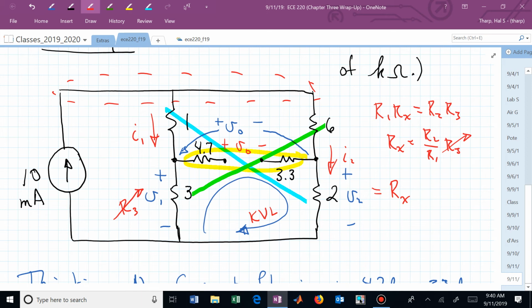So you adjust R sub 3 until you have zero movement on that dial in the bridge. You're trying to get zero current flowing, or 0 volts dropped across that bridge. You adjust R sub 3 to make that happen. R sub 3 now is this decade resistor box, and you can read off exactly what that is, and now you can get a very accurate measurement of R sub X. That's one application of this bridge network. But you can see that you could use this in many different kinds, maybe, of sensing environments.